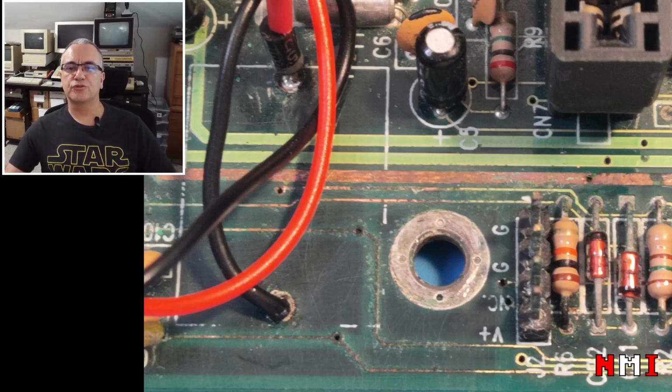Before we go, I want to show you something. After I recorded this video, I decided to have another look at the 486. As I mentioned, well, I didn't mention that, but one of the reasons it is a work in progress is I noticed that the CMOS configurations are not kept once I power off the machine. And I decided to investigate that a little bit deeper and understand why that was happening. And I found that, so this is where I replaced the battery. I added this diode here, right?